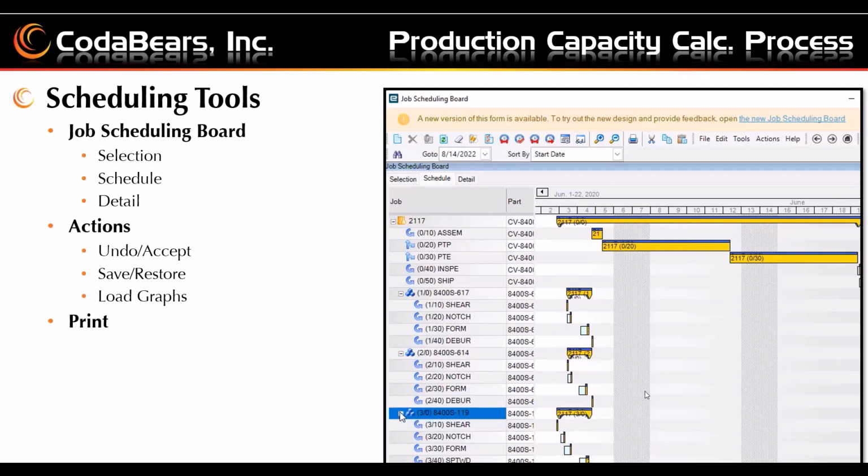When you manually schedule the job, I would almost say look in the log file to see if it paid attention to the constrained material for that version. If you have a constrained material, the log file is going to make an entry for this. Just open the log file in a text editor and do a search for the word constrained, to make sure that yes, I can go ahead and see these.